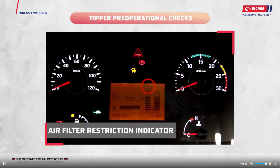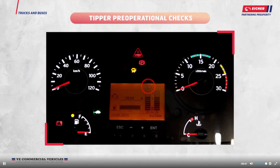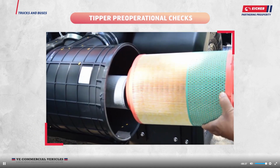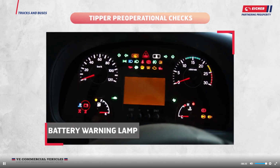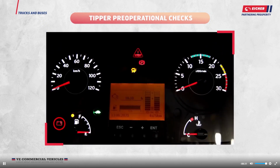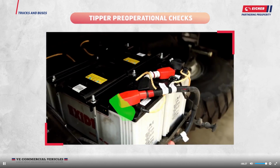Check air filter restriction indicator. If air filter restriction lamp glows, then check and replace the air filter element. Check the battery warning lamp illuminates when the ignition key is on and goes off as soon as the engine starts. It indicates that the battery is charging properly.